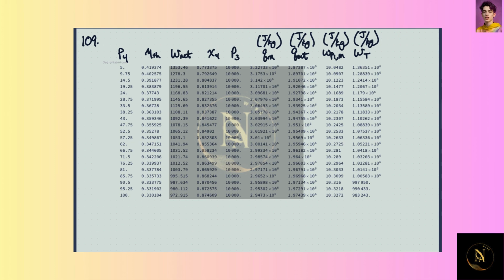In this problem, we again have an ideal Rankine cycle. And this time we're going to look at the effect of the condenser pressure. We're going to go from 5 kilopascals to 100 kilopascals. And again, I plotted various things out here, and this should be kilojoules. These are in kilopascals. The high pressure we kept, the boiler pressure was at 10 megapascals here.